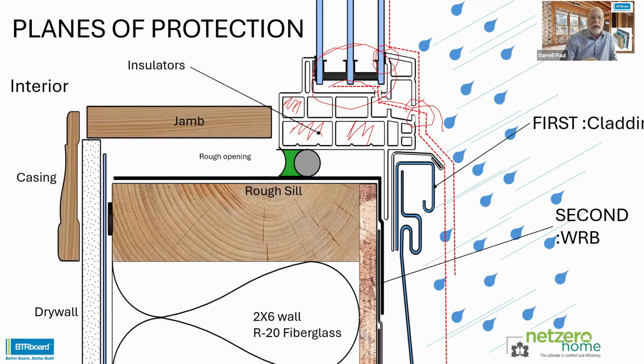So as you're looking at that, then the next part that we need to look at is right down here in the rough opening. So right here, we can see that there is potential for water accumulation there, and that can come from upper parts of the wall and the house. That can come through the rough opening, down the window, and collect at the bottom.